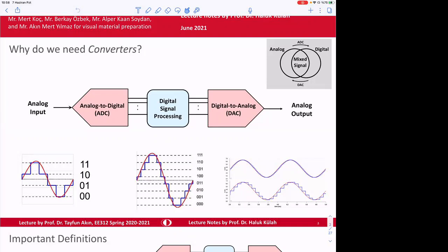So we split that signal, let's say maximum and minimum signal range, into digital representations, and then say that the lowest signal is going to be 0 0, for example. This is if we have 2-bit representation. 2-bit representation will allow us a voltage level of 2 to the power 2, then it means 4.